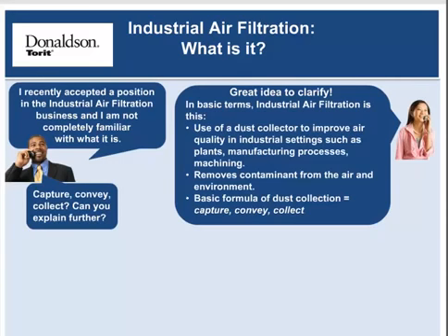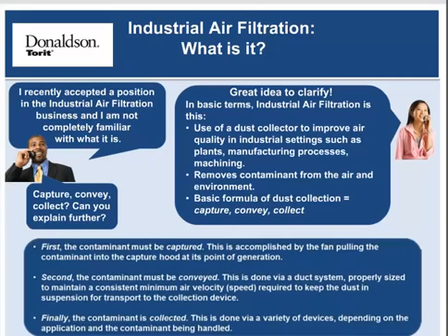Capture, convey, collect. Can you explain further? First, the contaminant must be captured. This is accomplished by the fan pulling the contaminant into the capture hood at its point of generation. Second, the contaminant must be conveyed. This is done via a duct system, properly sized to maintain a consistent minimum air velocity required to keep the dust in suspension for transport to the collection device. Finally, the contaminant is collected. This is done via a variety of devices, depending on the application and the contaminant being handled.